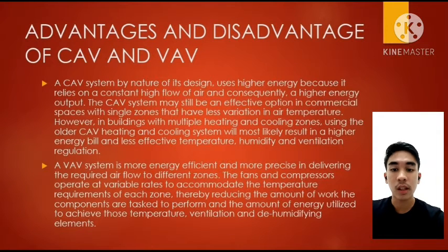Moving to the advantages and disadvantages of the CAV and the VAV system. A CAV system, by nature of its design, uses higher energy because it releases a constant high flow of air, and consequently a higher energy output. The CAV system may still be an effective option in a commercial space with a single zone that has less variation in air temperature.